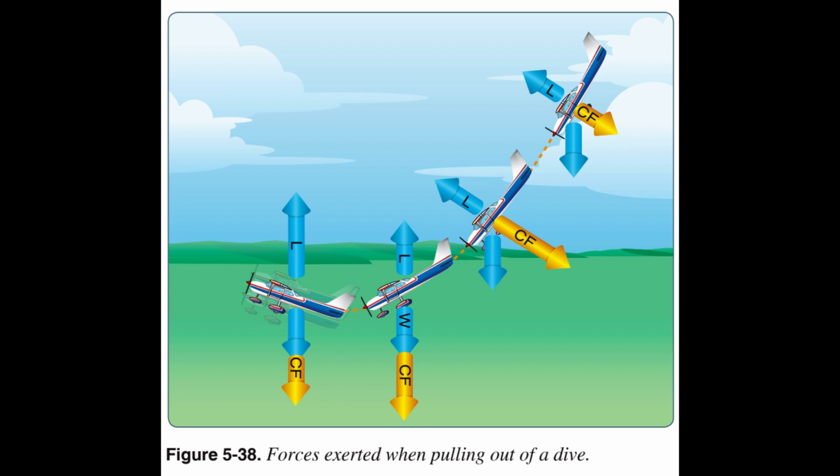In most straight-wing aircraft, the wing is designed to stall the wing root first. The wing root reaches its critical AOA first, making the stall progress outward toward the wingtip. By having the wing root stall first, aileron effectiveness is maintained at the wingtips, maintaining controllability of the aircraft. Various design methods are used to achieve the stalling of the wing root first.